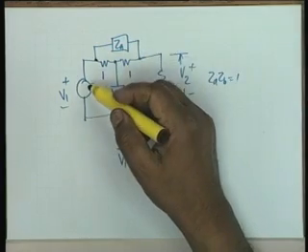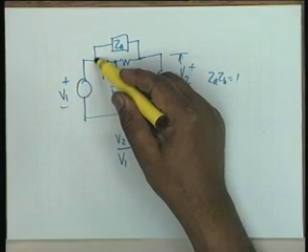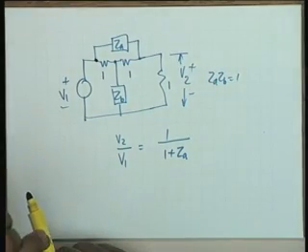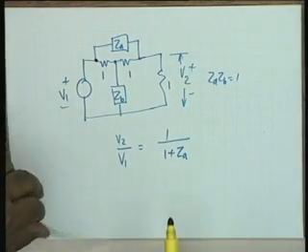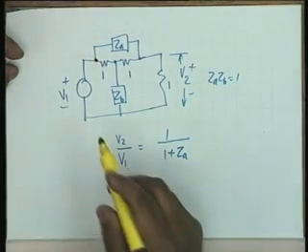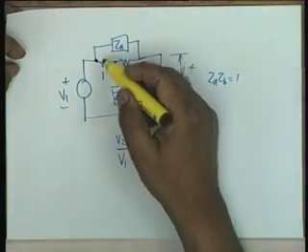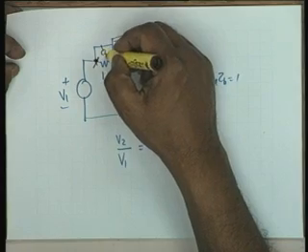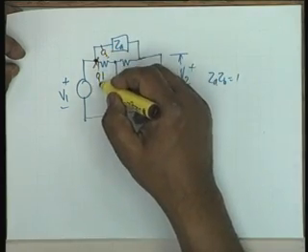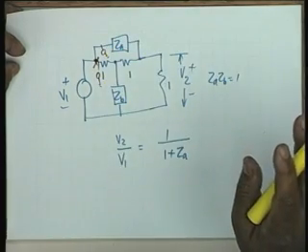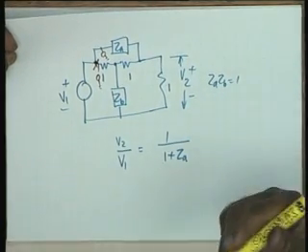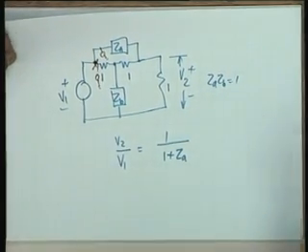That is, you could split this connection and connect a voltage source V1 to each network. Let us see if that gives us any simplification. You understand what I mean? If I disconnect it here and then connect a V1 here and connect a V1 here, it is not changing matters, it remains identical, but it solves the network almost by inspection. No calculation is needed. Look at the simplicity.